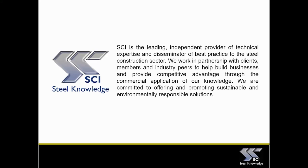There's a question about deflection limits. I think this question is getting confused between the sway deflection limits and the out of plane deflection limits that you might have on a wall panel itself. So wind blowing on the face of a wall panel and that deflection limit. So not particularly related to the stability system, but there's guidance in SCI publication P402 about that.